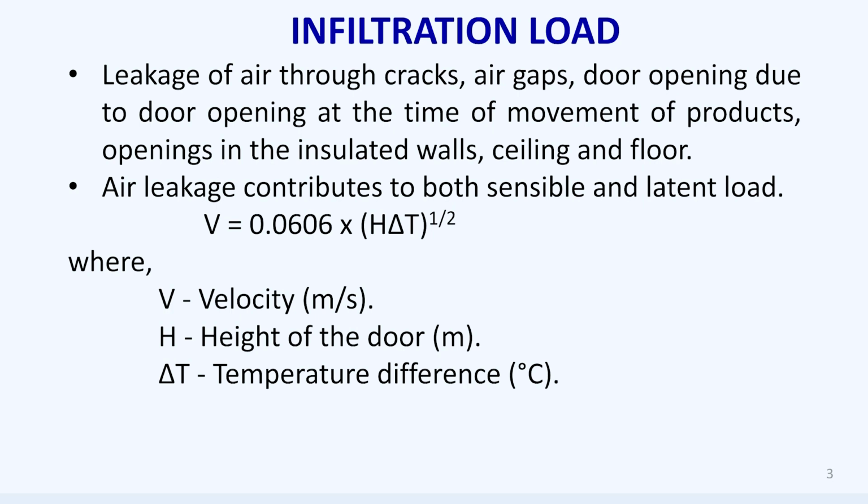This air leakage can be through the walls, ceiling or the roof, floor, etc. The leakage of air contributes to both sensible and latent heat load. Normally the temperature portion contributes to the sensible heat load. The moisture portion of the air, that is the water vapor present in the air, contributes to the latent heat.